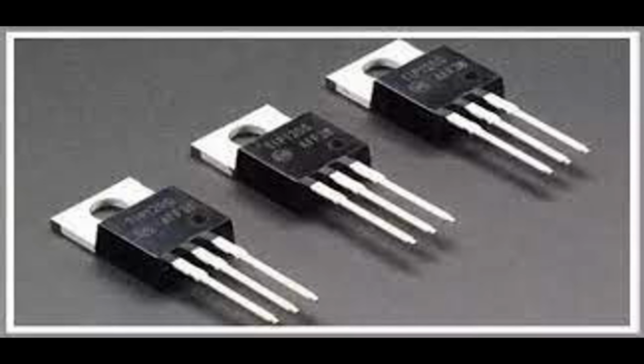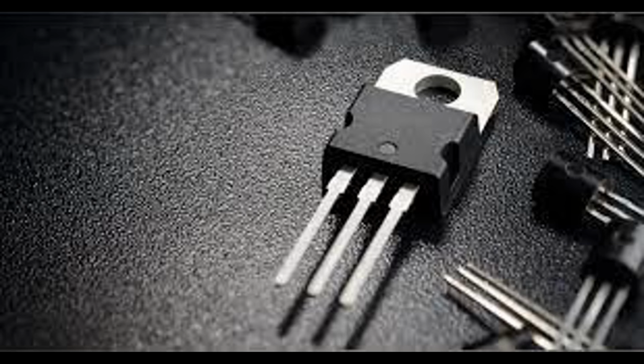8. Gate charge, Q_G. Description: the total charge required to switch the MOSFET on and off, which is influenced by the gate capacitance. Implication: lower gate charge results in faster switching times, which is crucial for minimizing switching losses in high-frequency applications. 9. Miller effect. Description: the gate-drain capacitance, C_GD, can cause the gate voltage to rise during switching due to feedback from the drain. Implication: this effect can influence the switching speed and stability of the MOSFET, necessitating careful gate drive design to mitigate its impact.